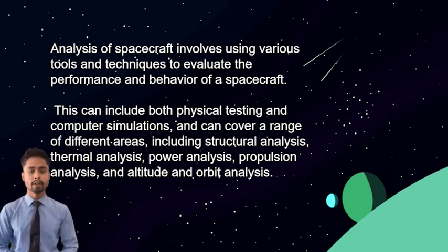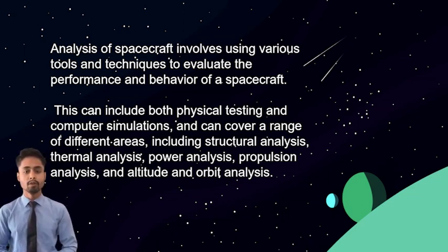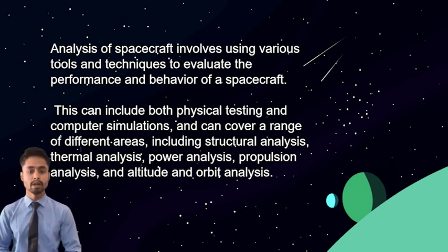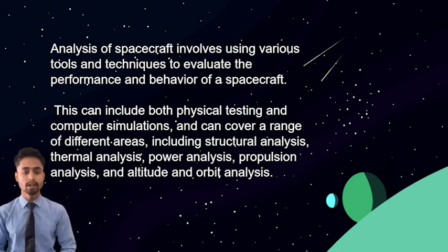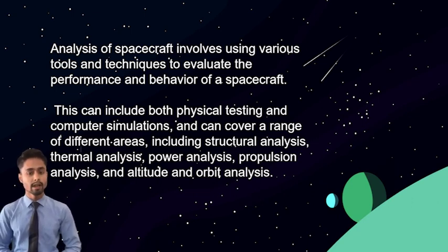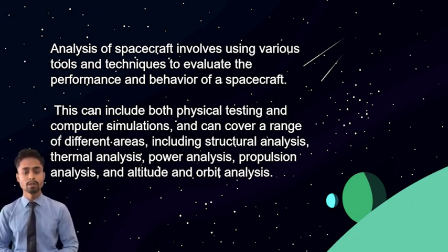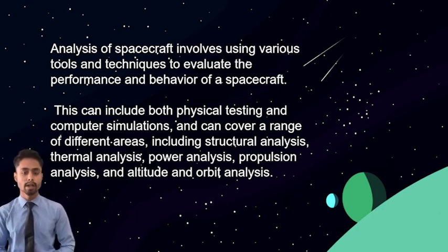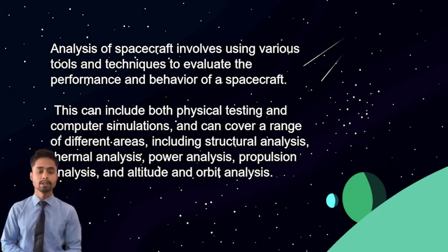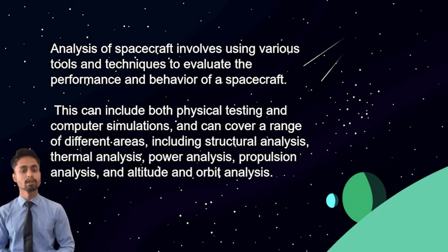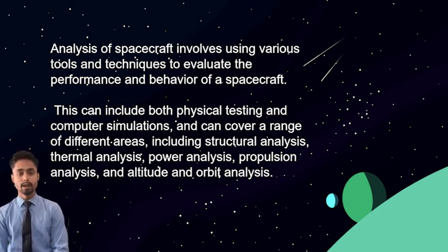Analysis is a critical aspect of spacecraft design and it involves using mathematical models and simulations to evaluate and optimize the design of spacecraft. There are several types of analysis that are typically performed under spacecraft design, including first, structural analysis. Structural analysis is used to evaluate the strength and stiffness of the spacecraft structure and to ensure that it can withstand the forces of launch and the harsh conditions of space. This involves using finite element analysis software to model the structure and evaluate its stress, strain, and deformation under various loads and conditions.